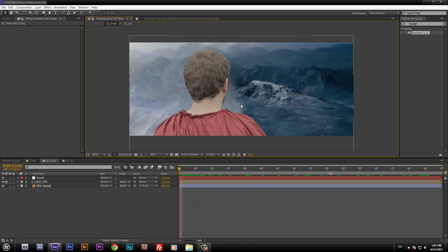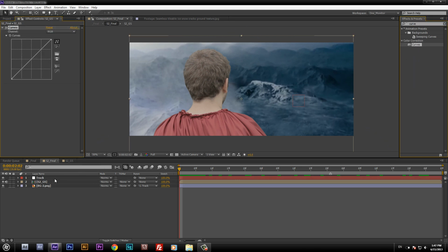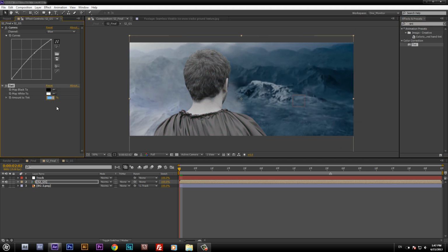Awesome. But what made this clip awesome is that I used a color correction and light wrap to make it look as realistic as possible. We'll do that by using curves in the footage, and I'll just lower the shadows, increase the highlights, decrease the reds, and increase the blues. We want to get the bluish look like from the background. Next we'll add a tint effect. We'll tint it to white for 30%.